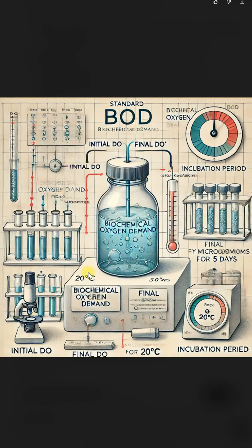Here is the schematic diagram illustrating the setup of a standard BOD test. It shows the process, including the initial and final dissolved oxygen, DO, measurements, incubation at 20 degrees Celsius for 5 days, and the oxygen consumption by microorganisms.